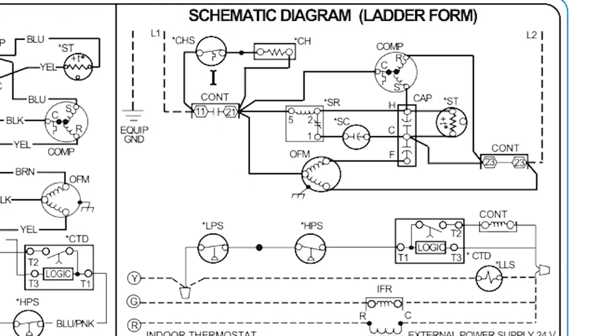And I can also tell that it is a normally closed, open on rise temperature sensing switch. I know it's temperature sensing because of what it looks like down below the switch. So this is like a connection point here. And the fact that it's closed means that it's normally closed. So under normal circumstances, it's going to be closed. Usually that's with no power applied. And then if the temperature increases, it's going to open.